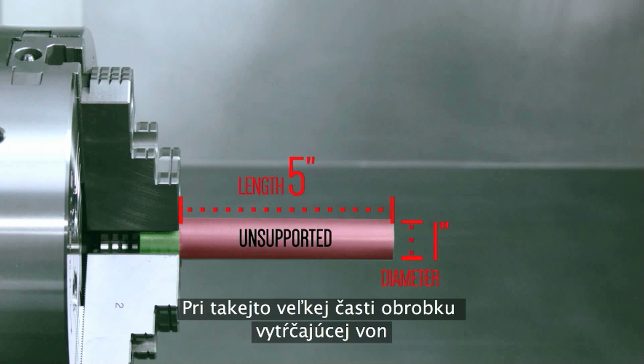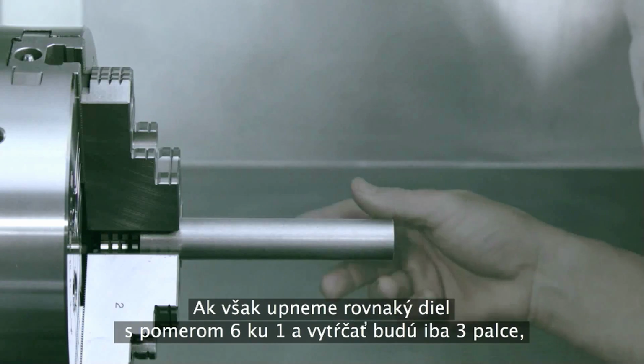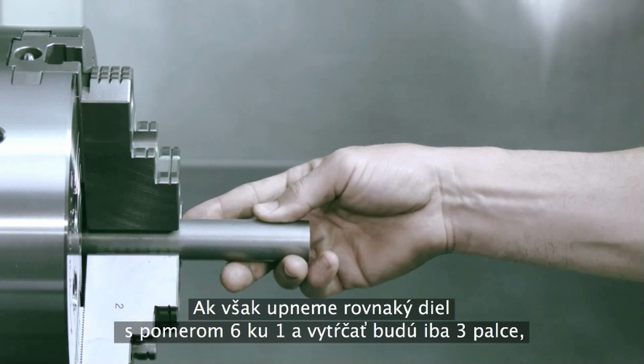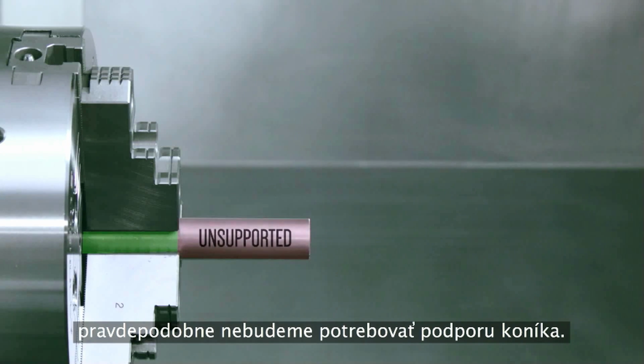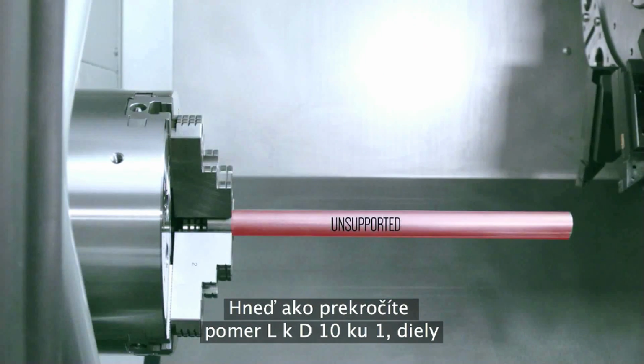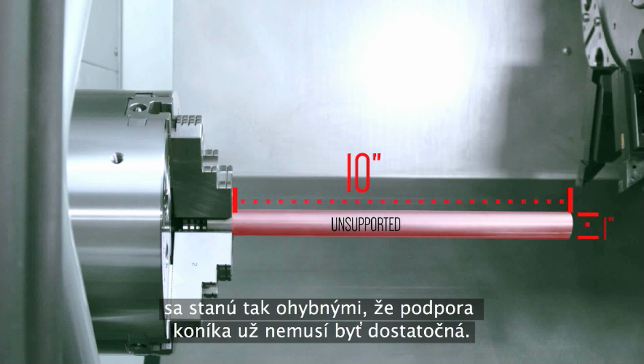With this much of the workpiece hanging out, there will likely be problems cutting unless tailstock support is added. However, the same 6:1 part, clamped with only 3 inches hanging out, will probably not need tailstock support, because now the unsupported region is only at a 3:1 ratio.